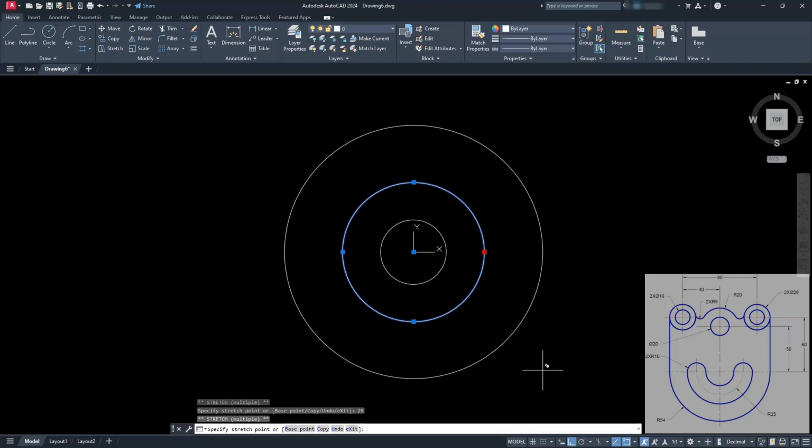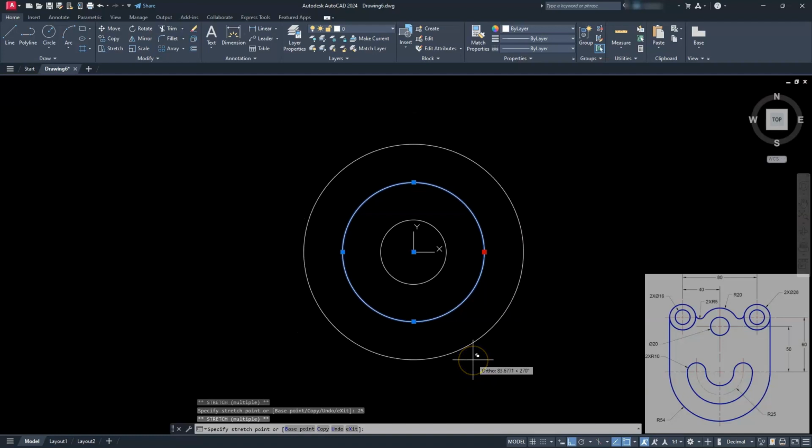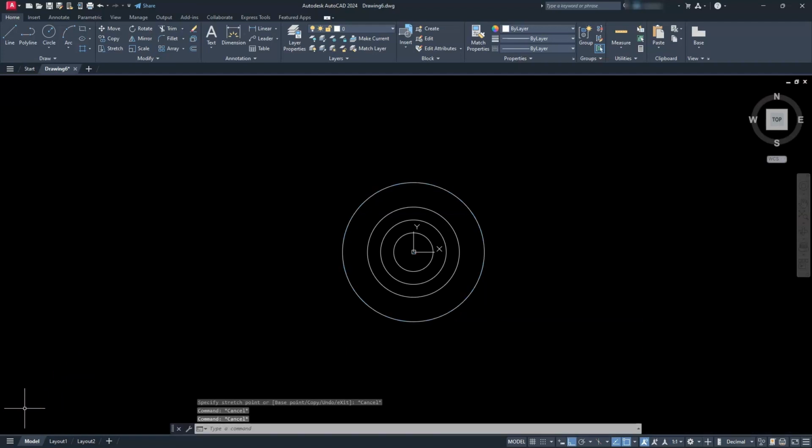If I had another one that is 10 or something of that nature, and in this case, if I do the math on it, referring back to the drawing, I have a radius of 10. So all I got to do is add 10 to that radius, and then I can subtract 10 from it. And I'll show you what I mean by that when I switch over to the drawing, but I'm just going to type it in now. So if I add 10 to that, I have a circle that has a radius of 35. And then I also have a circle of 25 minus the 10, which in this case should be 15. Alright, let's go ahead and hit escape, and I'll show you what I'm talking about.